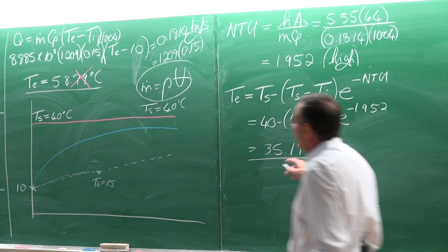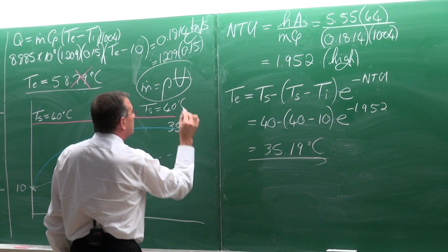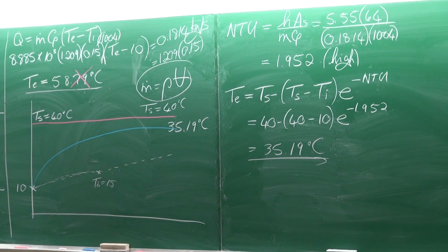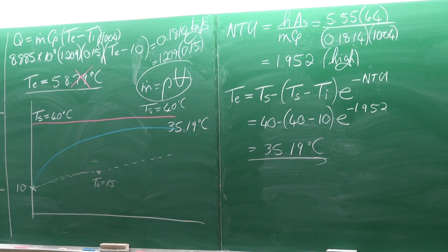Okay, 35.19. Now any air conditioning engineer will get a heart attack for an installation like that, and I think you also. So if you can just think of the ducts going into this venue, I don't think the air conditioning is working today, but at the chiller, the air is being produced at 10. If you've got a 40 meter duct and the air is coming in here at 35.19, that is not what we want.